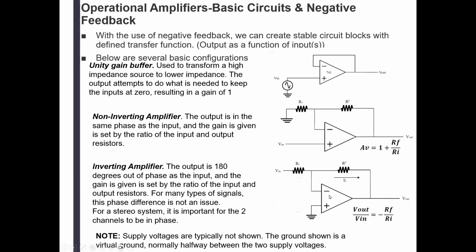So when you're assembling the circuit on your breadboard, you have to make sure that the positive supply voltage is connected to pin 7, and the negative supply voltage is connected to pin 4. Otherwise, this is not going to work. Same as the NAND gate or AND gate circuit that you did in the TTL labs, it's not going to work if you don't connect power to it.